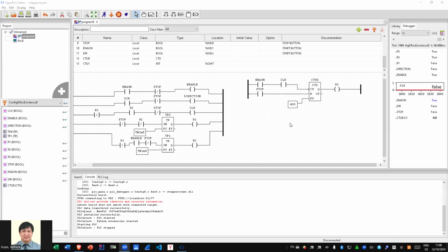Okay, so this is the third one for the series. We're still in stepper motors. So I've added an integer. Let's call it Modbus MB var1. So this is the variable one for the Modbus. So this is device addressable, so let's set the device ID to 8.